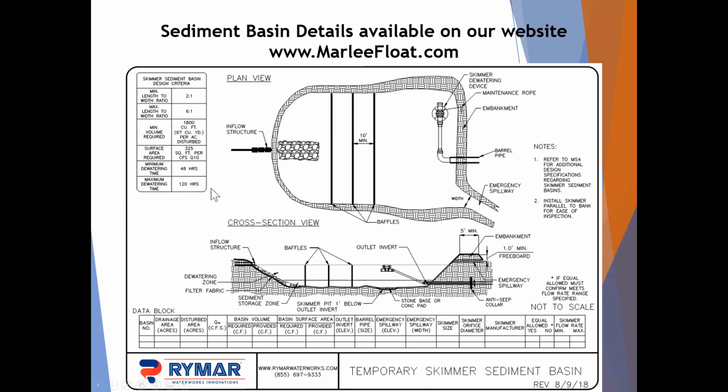We establish in these your minimum length to width ratio, and if you have a maximum, again, if you have a minimum volume required and surface area requirements. But here's the key thing: the minimum dewatering time and maximum dewatering time. Go ahead and establish those on your detail, and so when it's reviewed, that is approved.